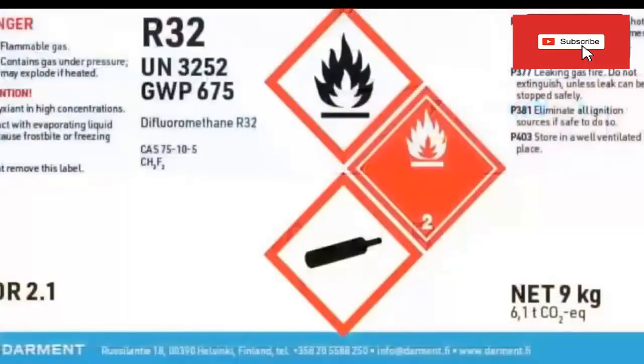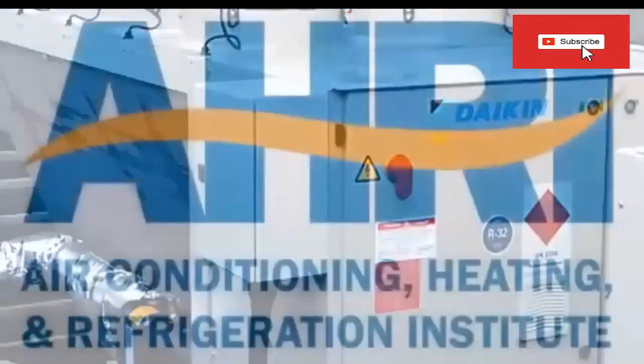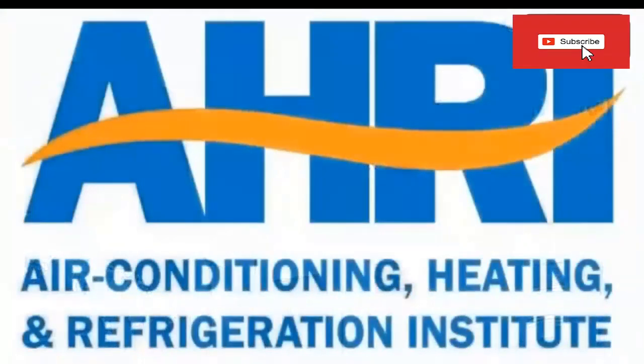Question 2. Does the R32 ignite from static sparks? Not really, as R32 must be exposed to an open flame or high-energy source to ignite. Remember, the Air Conditioning and Refrigeration Institute in the United States is clear in stating that updating or drop-in should not be carried out with refrigerants with flammability classifications other than the original equipment refrigerant.